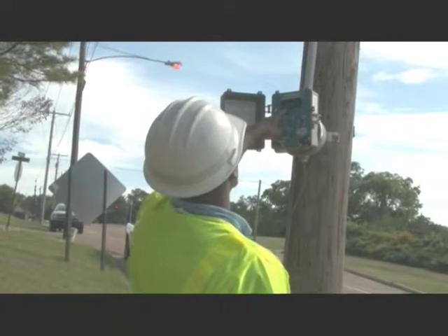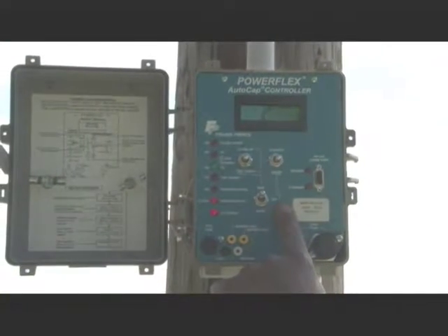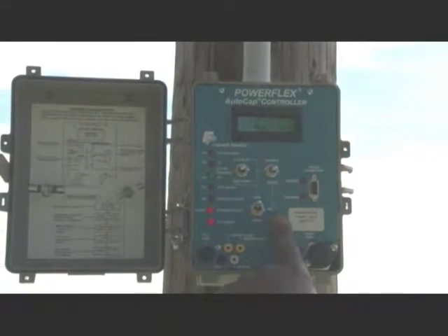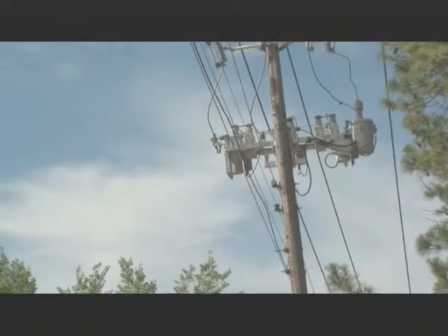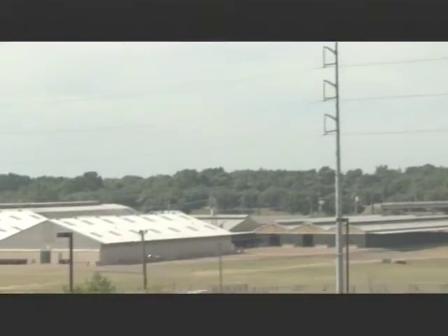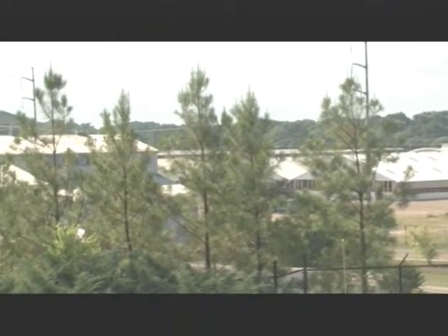The control mechanism can be preset to open and close the circuit to the capacitors during specific times of the day. It can also be set to operate on specific days of the week. For instance, this capacitor bank will remain offline during weekends because heavy three-phase motors used in this area are not expected to be operating.